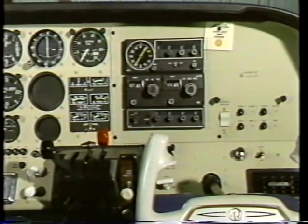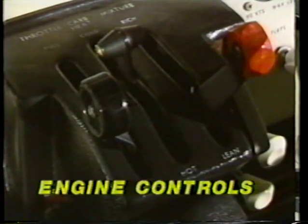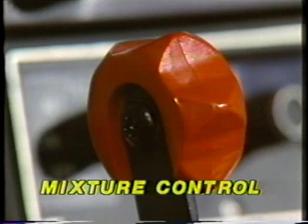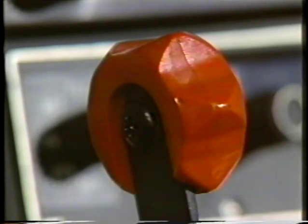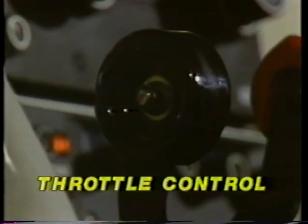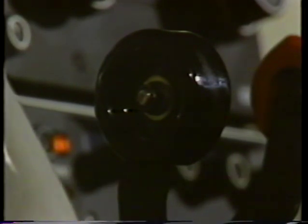Engine controls are located just below the engine instruments. The knobs are shaped to government standard configuration, so they can be identified by touch. Color coding is also used. The mixture control is red and has a scalloped shape. The carburetor heat control is a much smaller knob, which is a sort of oval or football shape and is black. The throttle control is a round shape and has a black knob.